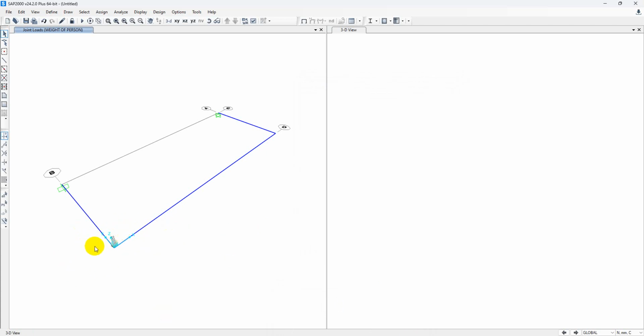Why are we applying this at this joint? To be more specific, we could distribute the force, like pull force 500 and 500, and 2250 as 1125 and 1125, but we are trying to be more specific, for a higher factor of safety. If this joint is able to handle this amount of force, then every joint will be able to handle this force. So I am just trying to be more specific.